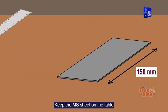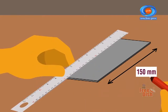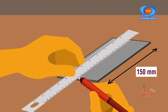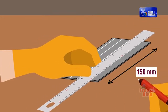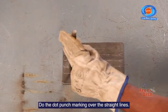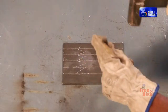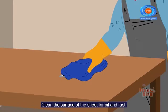Keep the MS sheet on the table and scribe straight lines using a ruler. Do the dot punch marking over the straight lines. Clean the surface of the sheet for oil and rust.